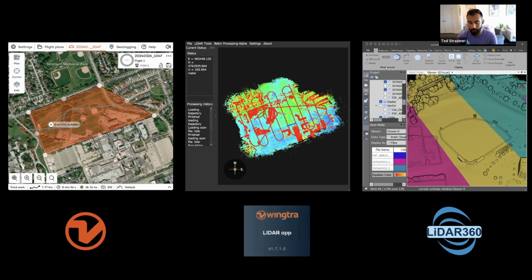And that's one thing with VTOLs that you kind of have to think about. Whereas with multi-rotors, you forget about the wind because they kind of just power through it. With VTOLs, I wouldn't say the wind speed is super critical. It definitely can be, but it's not as big of a deal as I imagined it would be, but you still should consider the flight direction with respect to wind.